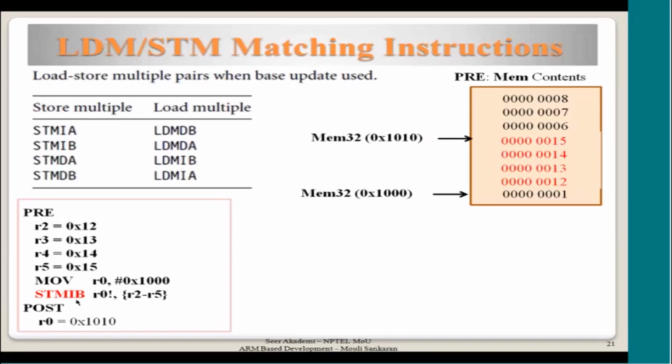Just intuitively see, it was increment before. Okay. So it was incremented before accessing this. So it would have gone and stood here. It is standing here. Now you want this to be copied back into R5, right? Now you should not do increment. Anyway, you have to do a decrement, but you can't do a decrement before, because if you decrement before, you will skip this value. You can't get it afterwards. So it should be decrement after.